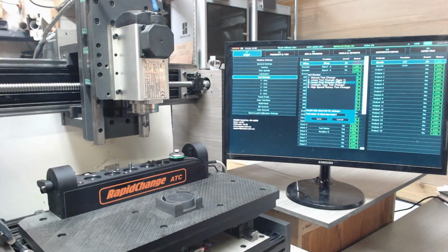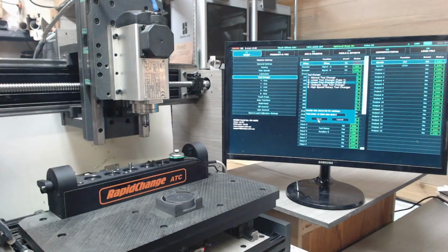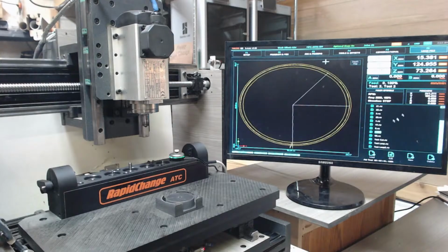You probably can't read this, but you set it up in the linear tool changer type 2, and you leave a bunch of stuff at 0. And then you just put every slot position as over the tool setter, and it runs without hitting cycle start, which is just fantastic. I couldn't believe it.